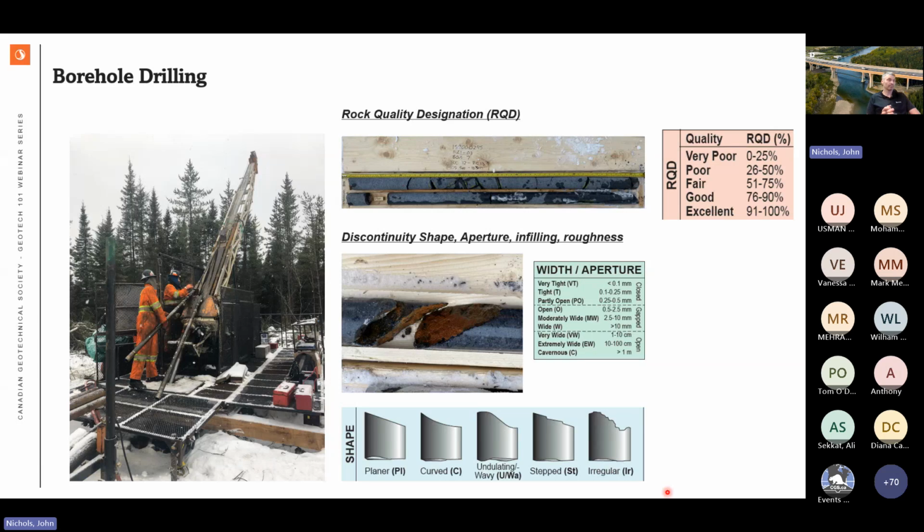We protect the core. When we do measure it, we're able to distinguish the natural fractures from the artificial ones that are created by the excavation, by the drilling process, and the removal of this core from the box. So it's important, and I think that's for anybody collecting rock information, borehole, rock core. Distinguishing between natural and artificial is key.